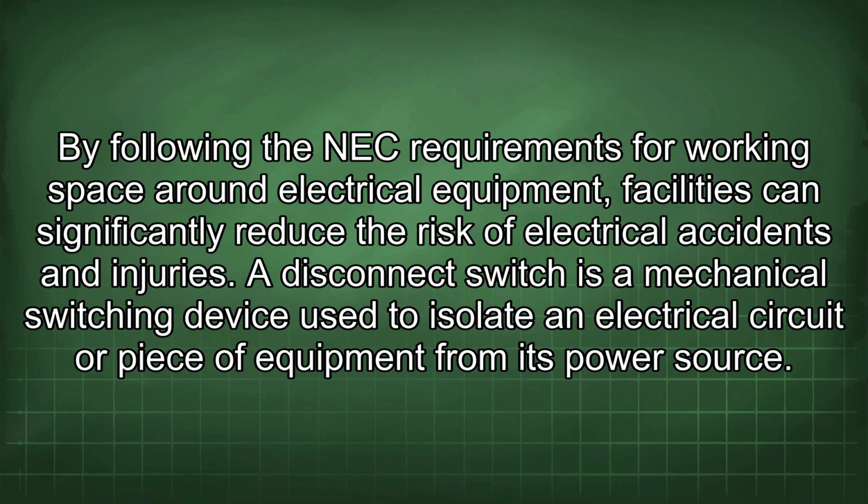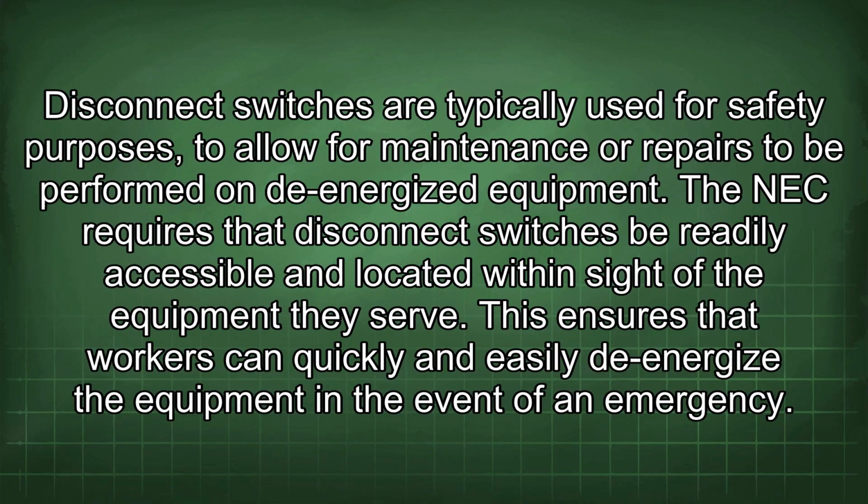and injuries. A disconnect switch is a mechanical switching device used to isolate an electrical circuit or piece of equipment from its power source. Disconnect switches are typically used for safety purposes, to allow for maintenance or repairs to be performed on de-energized equipment. The NEC requires that disconnect switches be readily accessible and located within sight of the equipment they serve. This ensures that workers can quickly and easily de-energize the equipment in the event of an emergency.